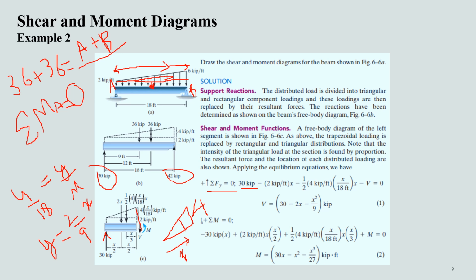So the unknown loading, or the loading due to this uniformly varying load, is usually determined by applying the principles of similarity of triangles, and thus we have minus 1 by 2 into 4 into x by 18 into x, minus V. So again, I have only determined the value of the height of this triangle, but when we have to apply it as a force, we have to consider the whole area of this triangle, which will be minus 1 by 2 into 4 into x by 18, which we have just done, which comes out as 2 by 9 x, and then minus V is the unknown shear force here.